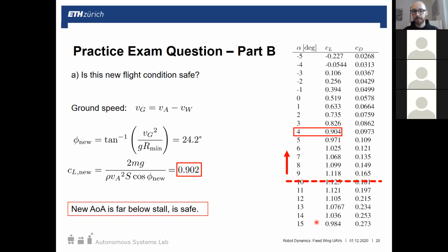But yes, so CL per angle of attack, at least beyond stall, just drops off a lot. That's our big decrease in lift. So especially for this lecture, really all you need to know about this relationship is you have that linear region of lift with angle of attack in the nice place where you can fly, and once you hit stall, steep drop off of lift.